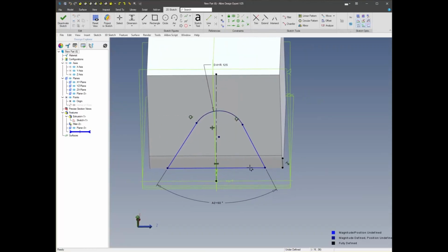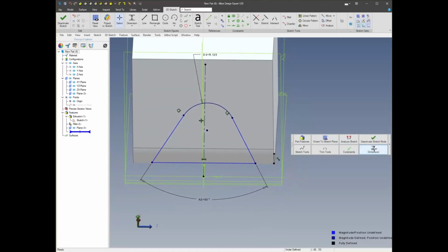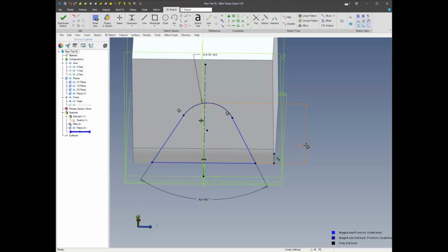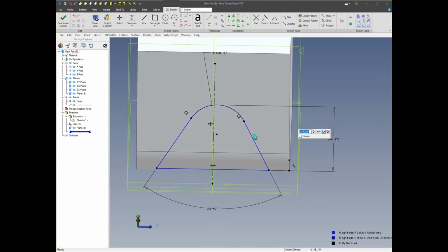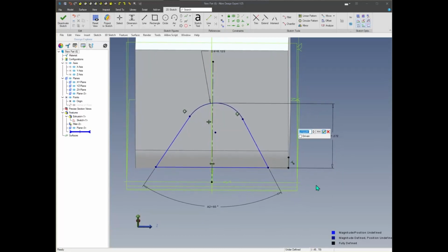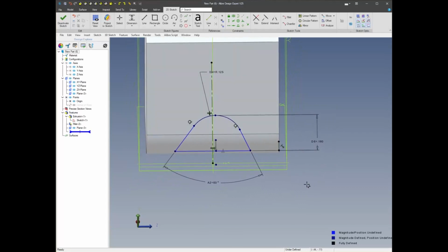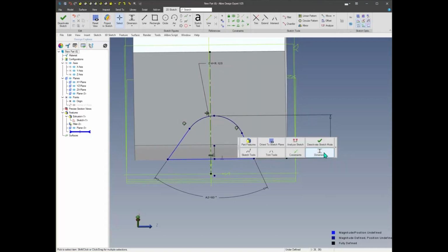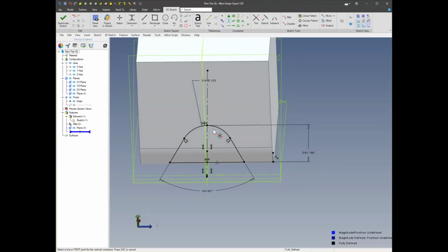And then finally we'll get in the height on here from the base to the top here. That'll be an outside dimension. And usually gussets are designed between 3 and 4 times material thickness, or no more than 3 or 4 times material thickness. So we'll put this in at 0.18 for height. And let's see here, one more constraint, and we need to put the center point of the fillet with a vertical constraint to the origin, and that'll center up our shape.